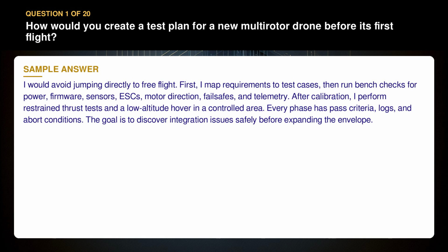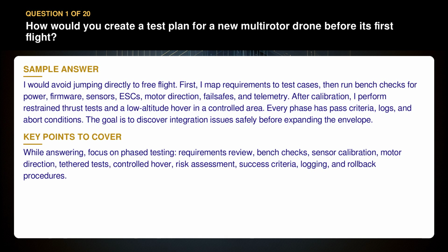Every phase has pass criteria, logs, and abort conditions. The goal is to discover integration issues safely before expanding the envelope. While answering, focus on phase testing, requirements review, bench checks, sensor calibration, motor direction, tethered tests, controlled hover, risk assessment, success criteria, logging, and rollback procedures.